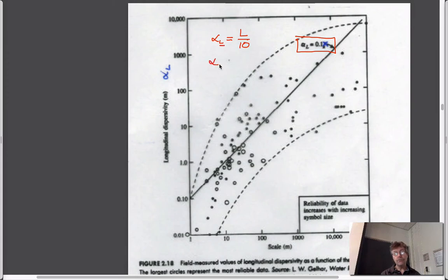You'll recall that what we're after is the transverse dispersion going perpendicular to the flow field, and that is often about equal to the longitudinal one. It may seem that we're just pulling numbers out of the air. It's typically less than it, right? Because the longitudinal spreading is much more virulent than the lateral spreading of these plumes. So the expression we might want to use is not the length of the pool divided by 10, but the length of the pool divided by 30.